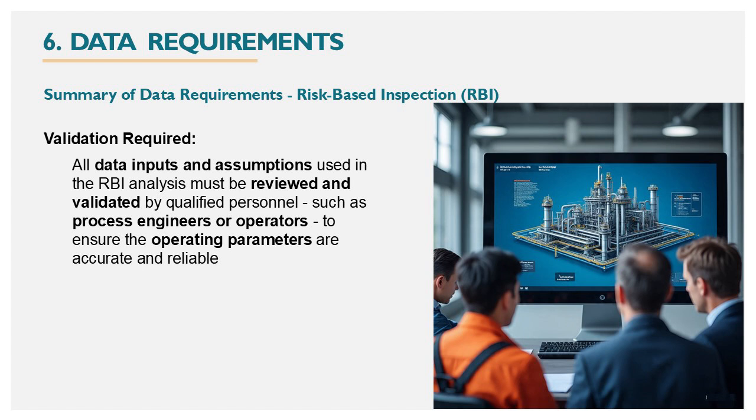Summary of data requirements in risk-based inspection or RBI. Data validation is required. All data inputs and assumptions used in the RBI analysis must be reviewed and validated by qualified personnel such as process engineers or operators to ensure the operating parameters are accurate and reliable.